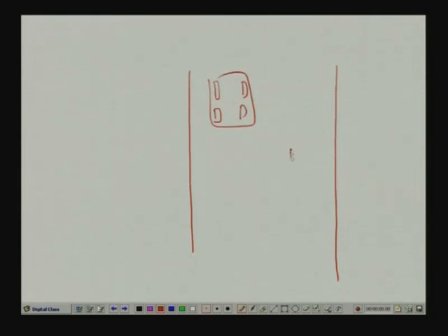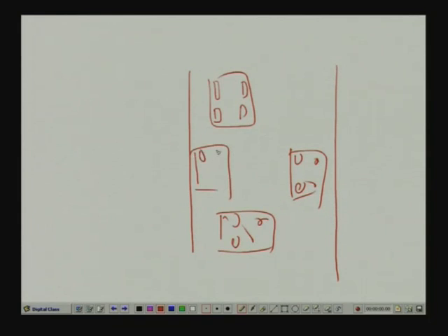For example, what we are trying to indicate is, if this is the pavement, at a given point of time, if this is how the vehicles are placed, if we put these wheels in exactly the same position, if this is a realistic practical positioning of vehicles, depending on the traffic intensity and the facility that is available, all the wheels are not going to travel along the same path.